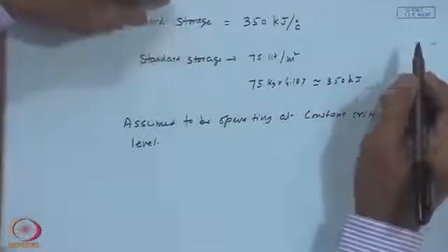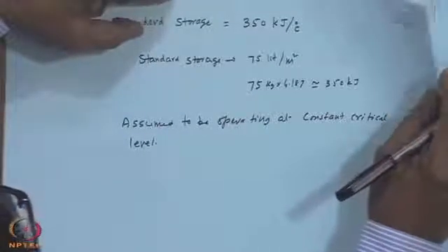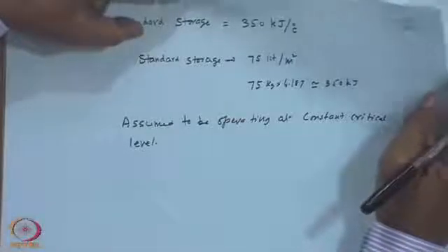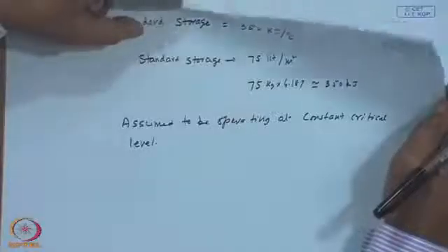Okay. So, you have a situation here, the monthly solar load fraction can be calculated for a system delivering energy at or above a certain desired temperature. The additional parameter that needs to be calculated is the monthly average daily utilizability, but the limitations are storage can be taken care of, but the critical level is assumed to be constant, yet methods are to be found out to calculate the utilizability other than detailed calculations, through a correlation or some other simplified method, if your critical radiation level is varying with time.